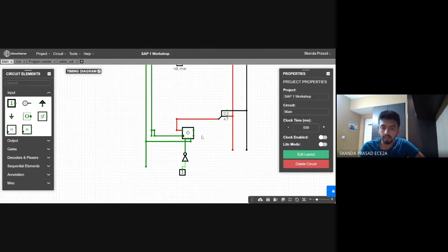And now this was about the input. Now all I need to do is the output. Output again goes back to the bus. But there is a catch here. There are two ways the output is split. One goes to the bus, and anything from any circuit element, if it goes to the bus, it has to go through a tri-state register. We discussed that many times. It is only because we don't need contention at the buses, because some data will be flowing in the bus anywhere. We don't want this to go at abrupt times and then have competition there, fighting, etc. We don't want that to happen. Only when we enable, only then the output should go.